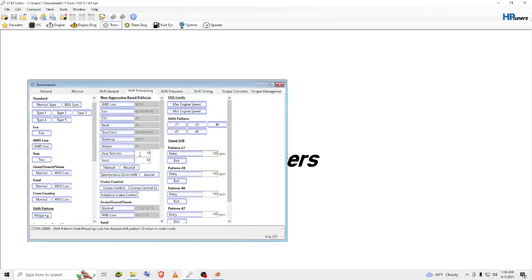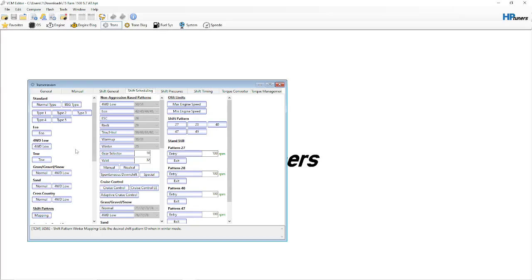The solution to that is you can change how long you want that gear to rev out before it shifts. So you can either make the gears very quick, where it's 1, 2, 3, 4, or you can make it rev out to, let's say, 20 miles an hour in first gear, and you have the applied torque to the torque converter.